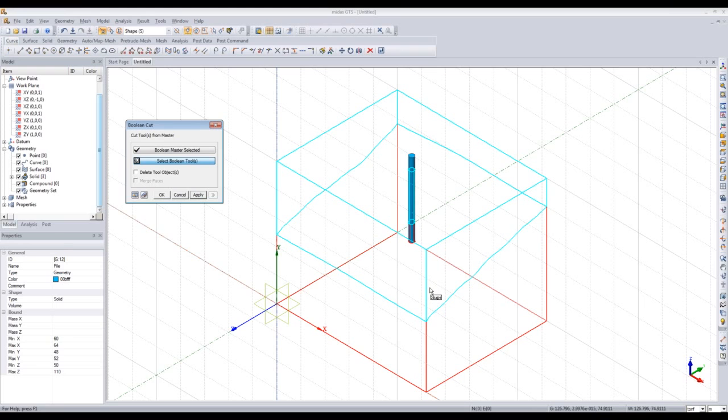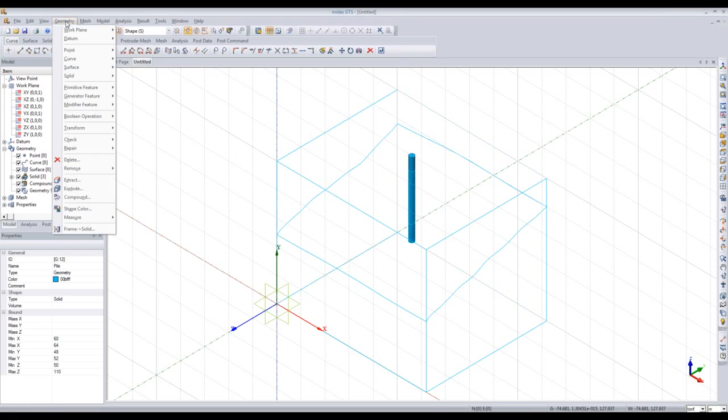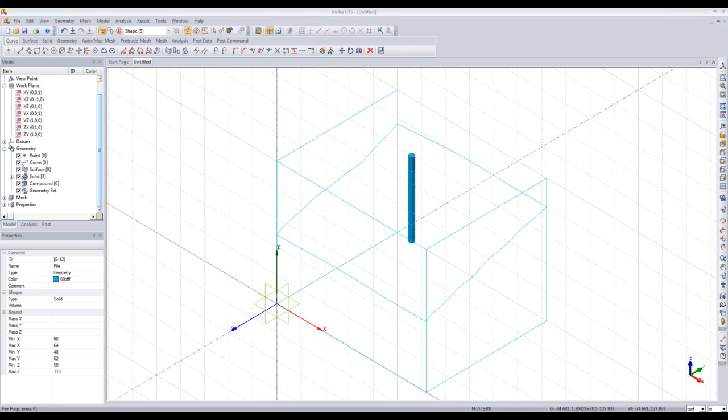particular application. And once again, the boolean cut can be used for not only pile foundations, but other structures or elements that you would want cut according to a certain ground material or soil layer. So that's how you would use a Boolean cut. That's just a basic demo of how to model 3D objects with Midas GTS. And once again, your main point of reference would be the Geometry tab. This is how you create all of your geometry and objects.